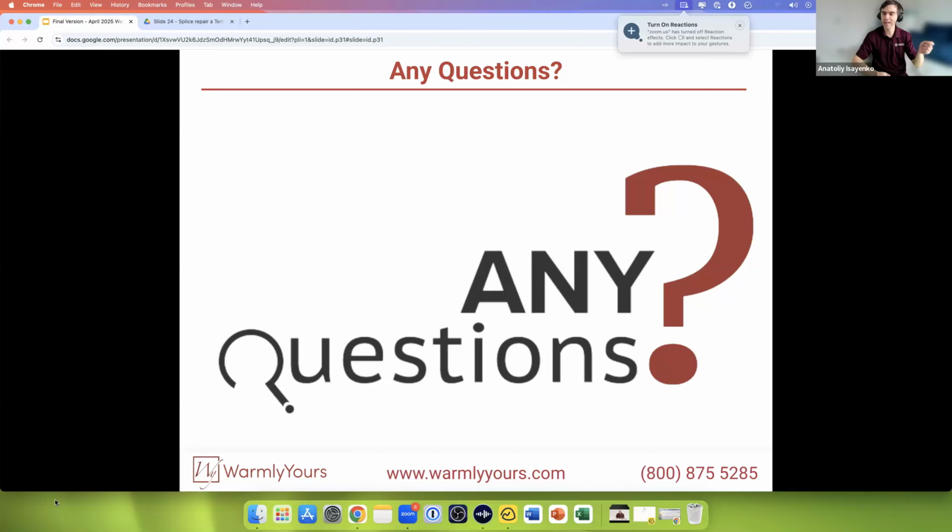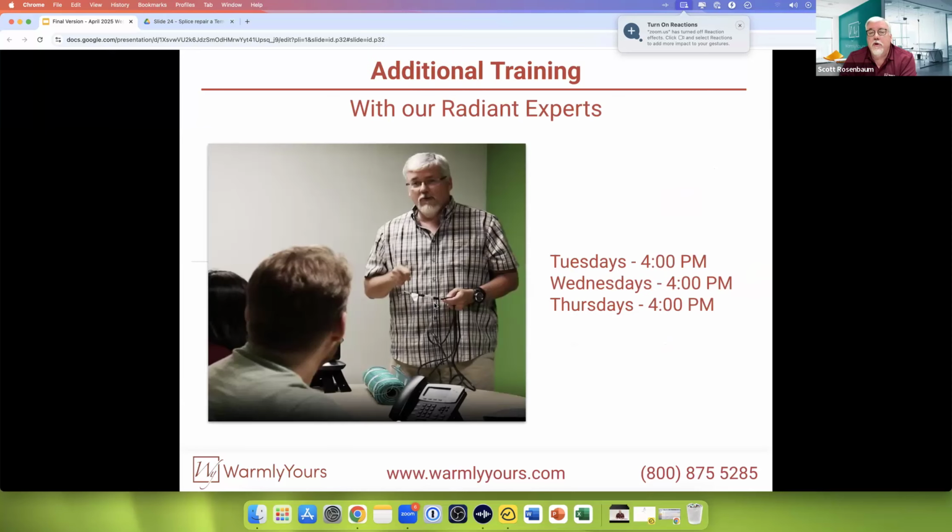When does it actually trip? I know you mentioned 2 or 3 days, but is it maybe tripping every time that fan kicks on? Maybe it's tripping every time some other combination of equipment, appliances, fans, or lights being turned on in the house? That may give some additional clues. Yeah, so that's why the megohm is so important to get the floor ruled out. Because if you can rule that floor out and that floor is good, it's something about getting the power to it. So hopefully we've given you a couple of good things to look for there, Peter.